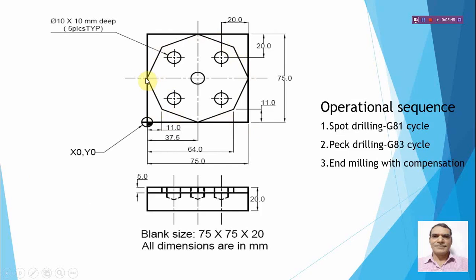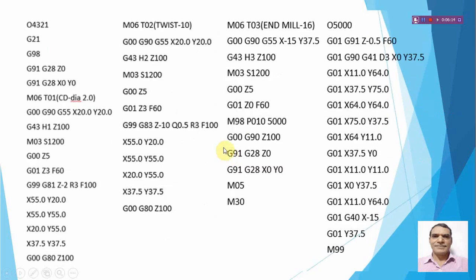Finally, just increase the value up to this, then come out from the workpiece. When the tool is coming out, simply cancel the cutter compensation by using G40. Now G41 is cancelled. Once again come back to 37.5. Then the next 10 passes will be carried out. Already one pass is over, the remaining 9 passes will be carried out. We will get the 5 mm depth.